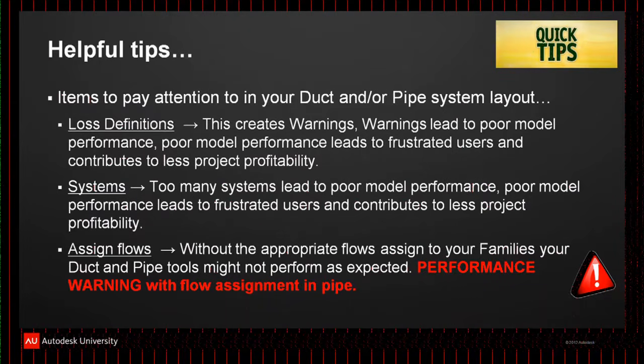When you upgrade 9 to 10, get in there and address all your warnings. Go from 10 to 11. There is no question about it. You are going to break things when you migrate that project forward. There's no way around that. Between 2010 and 2011, electrical functionality changed. I know this is a mechanical class. You migrate that project forward, your electrical systems are kind of hosed. Okay? So just another tip for you guys.